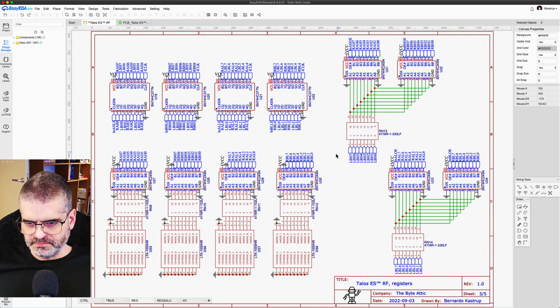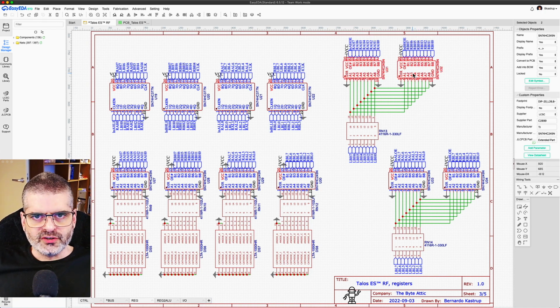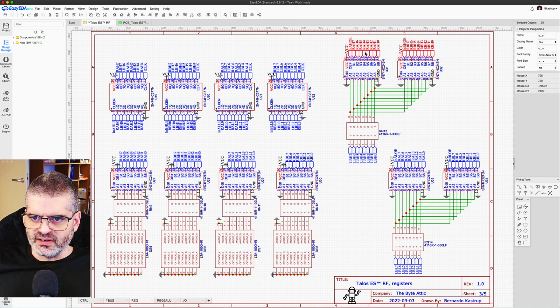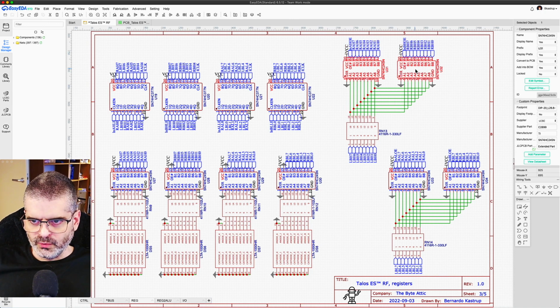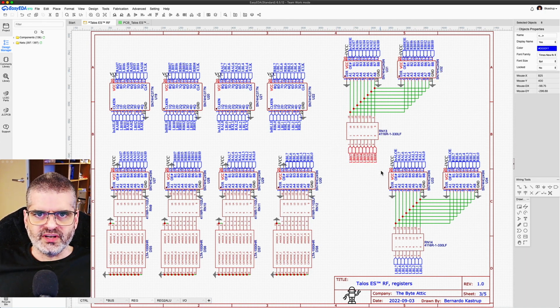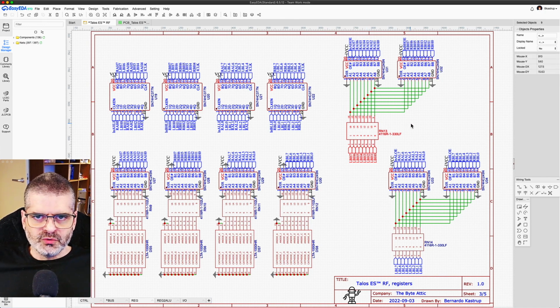And here, these two buffers will determine whether A high or B high, if you look at the signals going in, these are the lines coming from register A high and register B high. These two buffers will determine whether one of them, or none, drives the local bus high via a 33 ohm resistor network to reduce reflections.